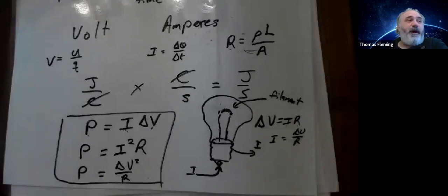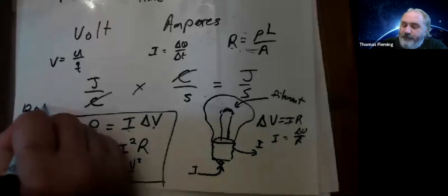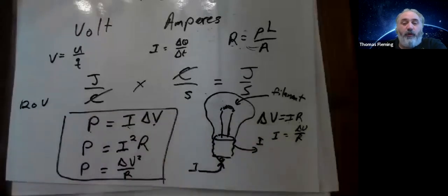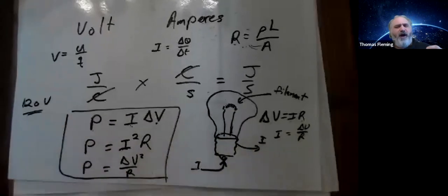However, in the United States, all the standard plugs tend to be wired at 120 volts. That's pretty much the standard. So yeah, it's 100 watts, but only if you're using a power source that's 120 volts. So for that 100-watt light bulb, I know the power, P, and I know the voltage it's intended for, V. So I know P and I know V.